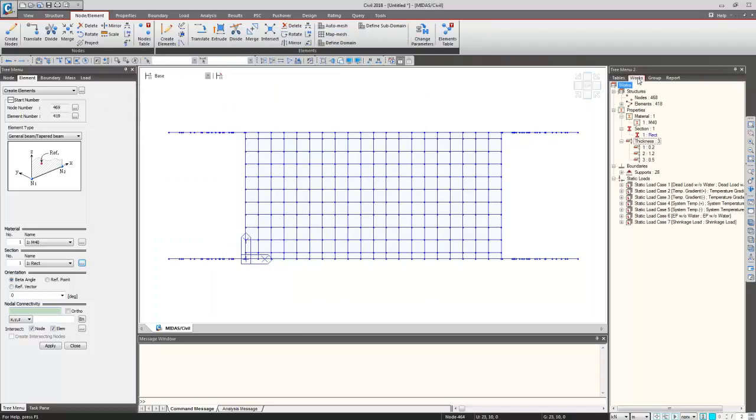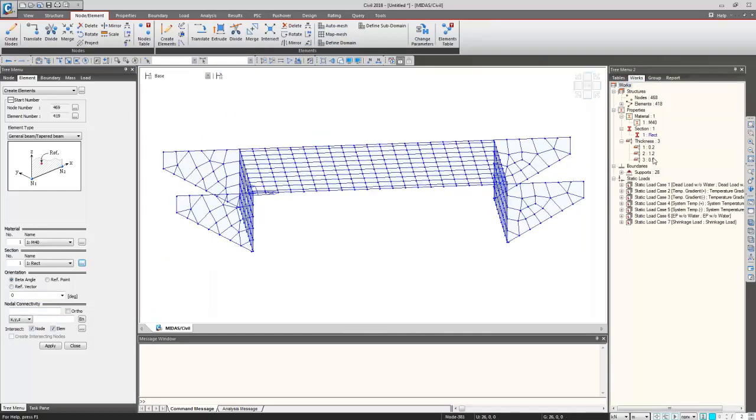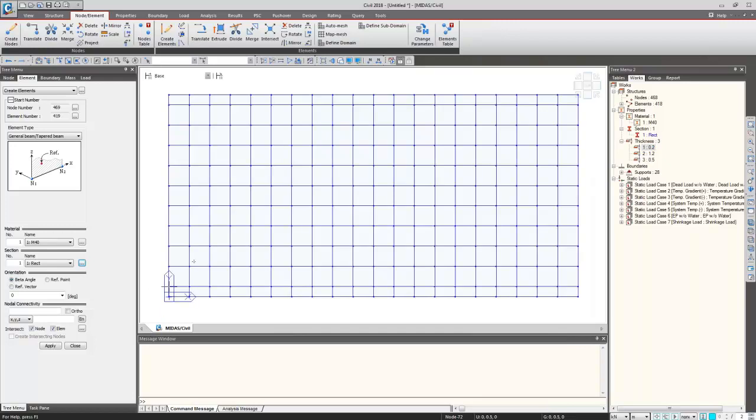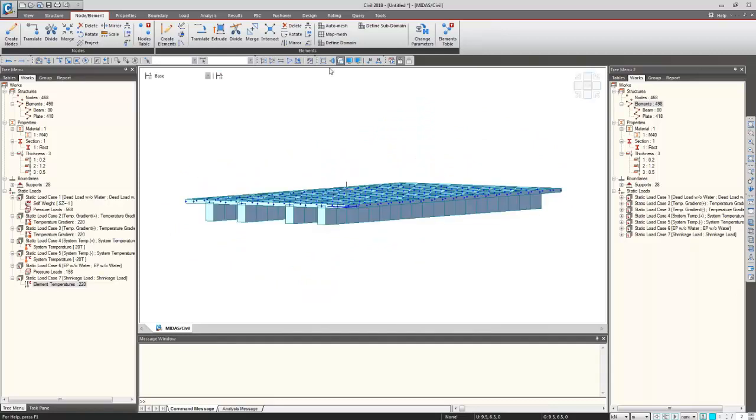So let's go to works. So to select the deck, you can directly click on this deck thickness. Only those elements would be selected and this is activated. Now you can easily create your girders. So I'm just randomly creating some girders here. 1 here as well, 2, then I'll skip 1 and this is 3, this 4th girder. Alright, so this is my girder. I'll activate all.